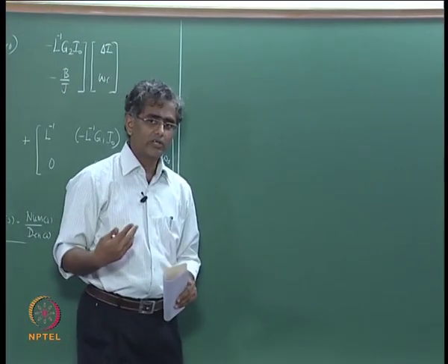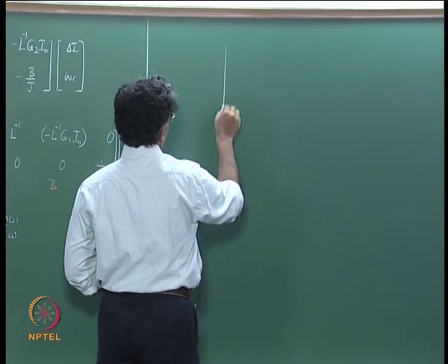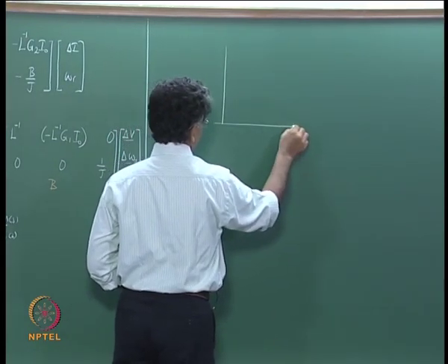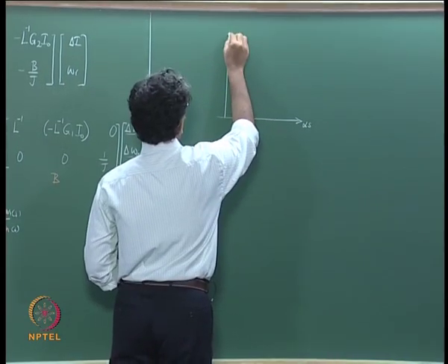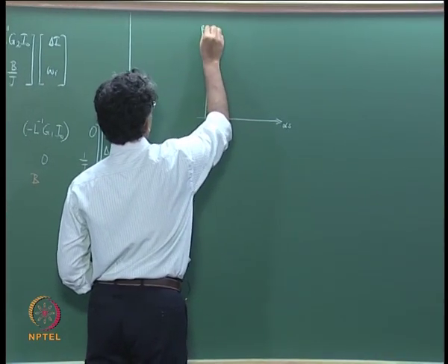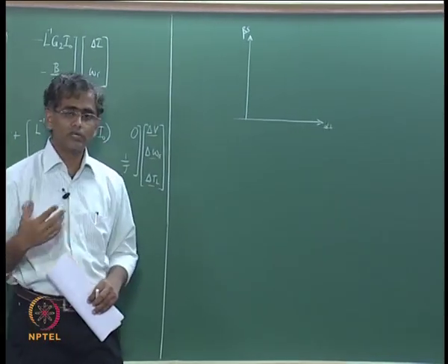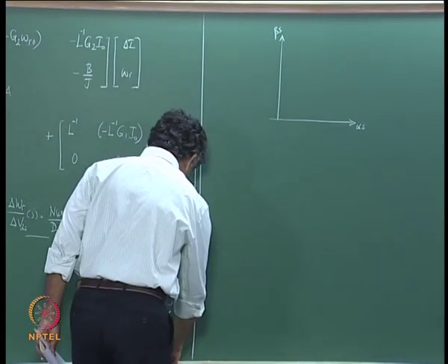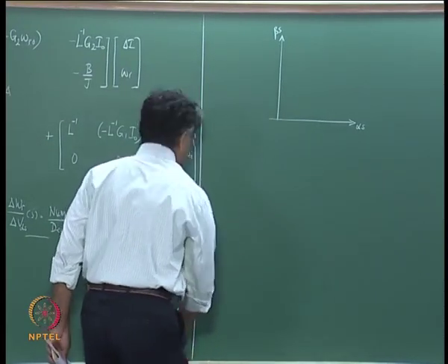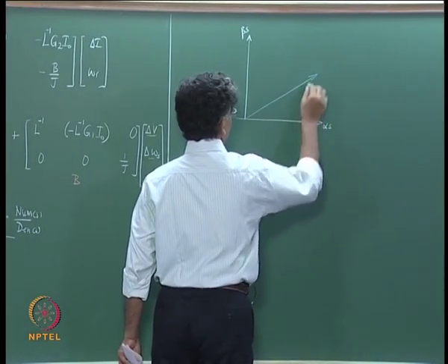In the machine equations that we have derived so far, you have the stator axis, this is your alpha stator axis, and then you have the beta stator axis, and we have transformed the equations to the synchronous reference frame, which means that you now have a reference frame which is, let us say, aligned at some angle.